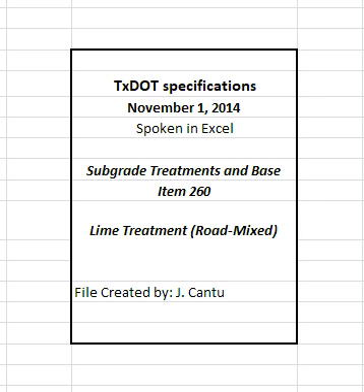When lime is furnished in bags, indicate the manufacturer's certified weight. Bags varying more than 5% from that weight may be rejected. The average weight of bags in any shipment, as determined by weighing 10 bags taken at random, must be at least the manufacturer's certified weight.